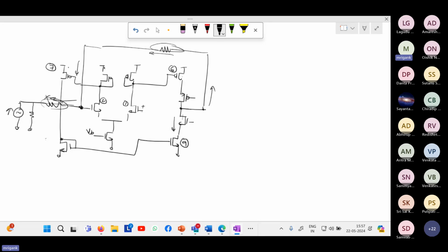And then in order to open the feedback over here, if you have to do the open loop analysis and get the loading effect, the way it is done is that on the other side, if you have shunt feedback while opening, you will put the R over here and this RF will come here, because the other side is shunt. So while opening the loop from the output side, looking at the output side, it will be grounded.